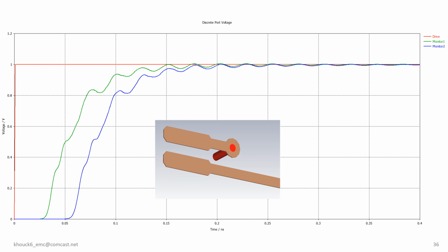In this configuration, the reference for the trace lies below the trace, with the pin containing the via serving as the reference net. It's essential to understand that even with precise layout planning, a signal's transition along the trace is slowed. For instance, a 1 picosecond source signal may take approximately 100 picoseconds to transition as it propagates down the trace, highlighting the intricate nature of signal propagation in super high-speed PCB designs.